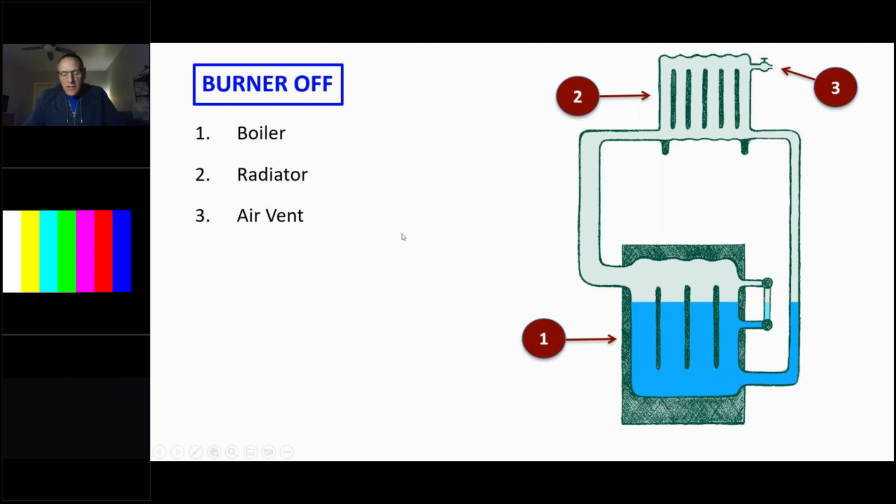The 3 basic concepts of steam are steam up, air out, and water back. You have to produce clean, dry steam, and dry steam is defined as having 2% or less of the water entrained in the steam. A clean boiler and proper piping per manufacturer's instructions are also critical to produce clean, dry steam. The second one is to remove air.